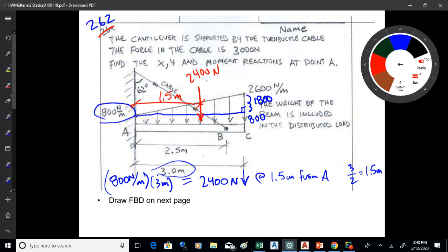Now I'm also going to have to figure out the triangle, so you can go ahead and do that. Okay, the triangular load will be about there, I think. And you're probably shooting for about 2,700 newtons on that. But run the numbers, make sure that I didn't make an error there, but there we are, 2,700 newtons. So do we have any questions on that first bit there?